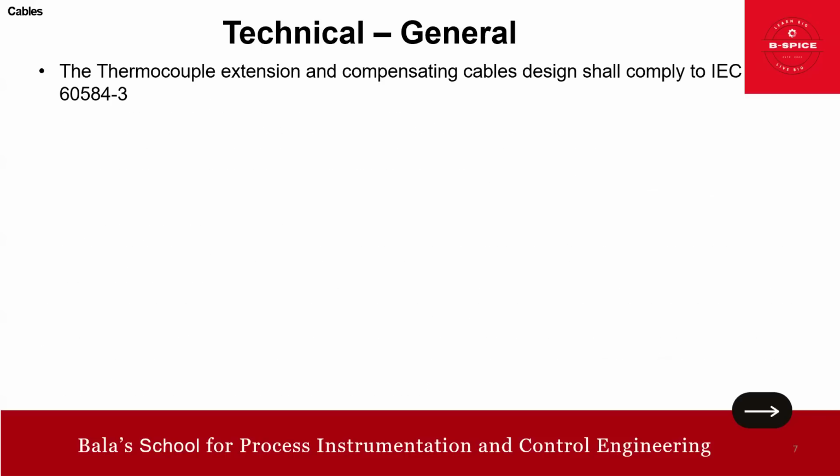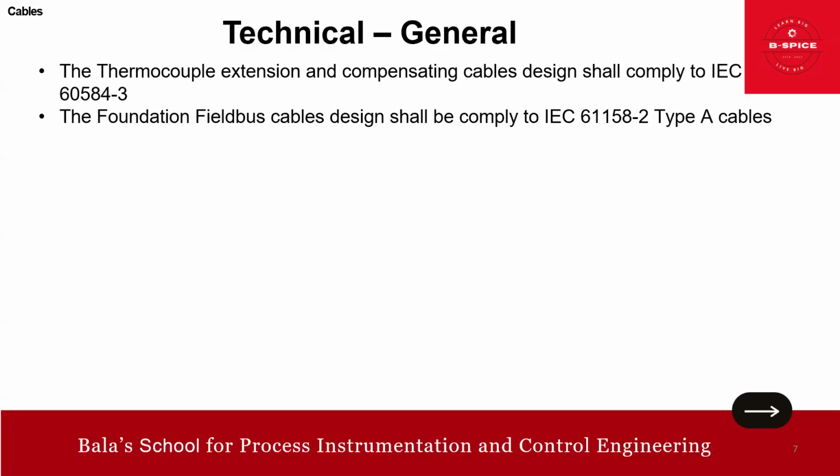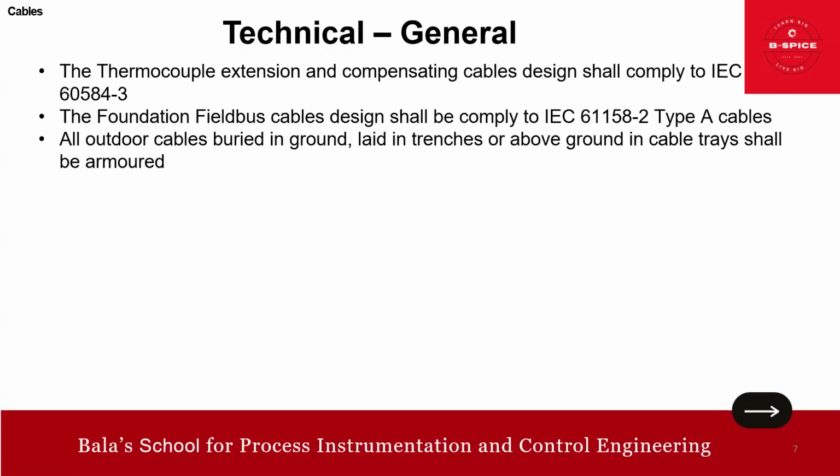Okay, take note. The thermocouple extension and compensating cable design shall comply to IEC 60584 Part 3. The Foundation Fieldbus cable design shall comply to IEC 61158 Part 2 Type A cables. This is all general, friends. I'm just giving a general hint.